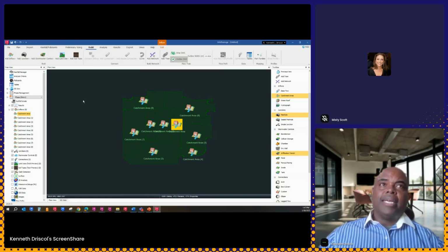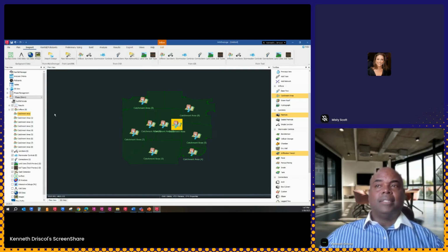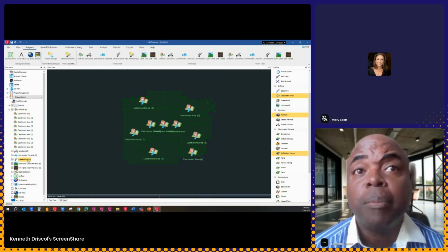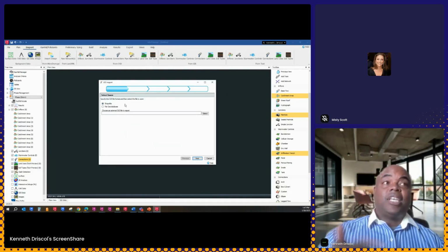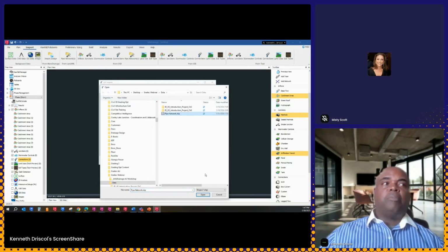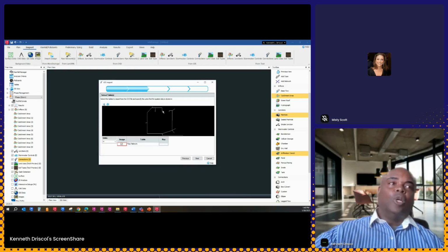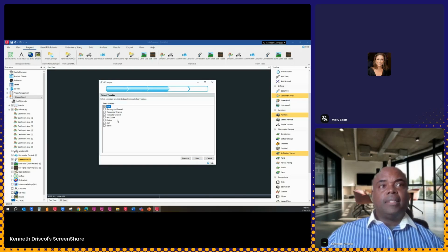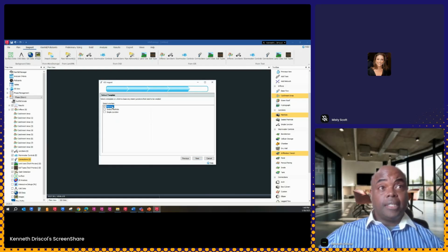Also, I want to be able to bring in, on my import tab, GIS data. So in terms of a surface, in terms of connections. So what about connections? If I pick on connections, right click, I can bring in a shapefile. So if you've got a shapefile from the GIS, I'll bring in this pipe network. I'll select next. It kind of loads that same one that I kind of drew. From that, I can tell it specifically it's a pipe. And then it's a manhole.